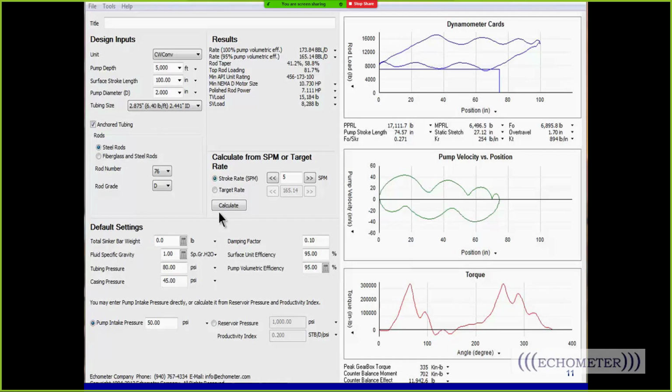First of all, on a pumping unit, the gearbox shaft center is not directly beneath the tail bearing when the walking beam is horizontal, and so that means there are different crank angles in the upstroke and downstroke, and the torque factors are a little bit different. And so what that means is that the torque changes whether you rotate. The counterbalance moment changes whether you rotate clockwise or counterclockwise. So for the current loading, for the current rod position, one rotation or the other, clockwise or counterclockwise, may give a better in-balance condition for the pumping unit. And so whichever direction of rotation puts the least net torque on the gearbox is the best direction of rotation.